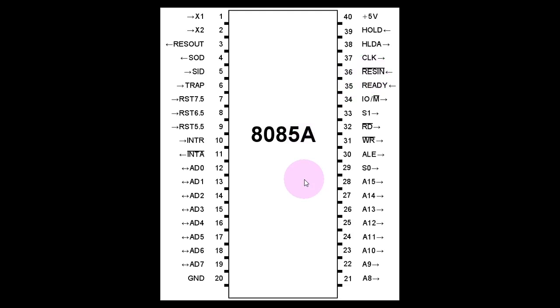We have already talked about it. The resetting will mean that this microprocessor will start executing the program from its beginning location. Theoretically, it is 0000H, that is 0000 in hexadecimal. But for the 8085 software that we have seen, it is 4200H by default. So whatever programs are written into the external memory are written from 4200H, and from there its program will start executing. That's what we mean by resetting your microprocessor.